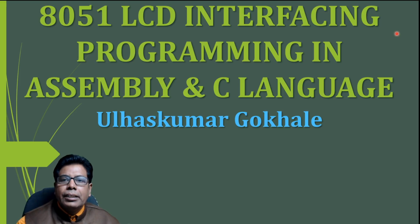The topic for today is 8051 LCD interfacing programming in assembly and C language. LCD displays are dot matrix displays where display elements in the form of dots are arranged in rows and columns. Commonly 5 by 7 and 7 by 9 matrix are used.